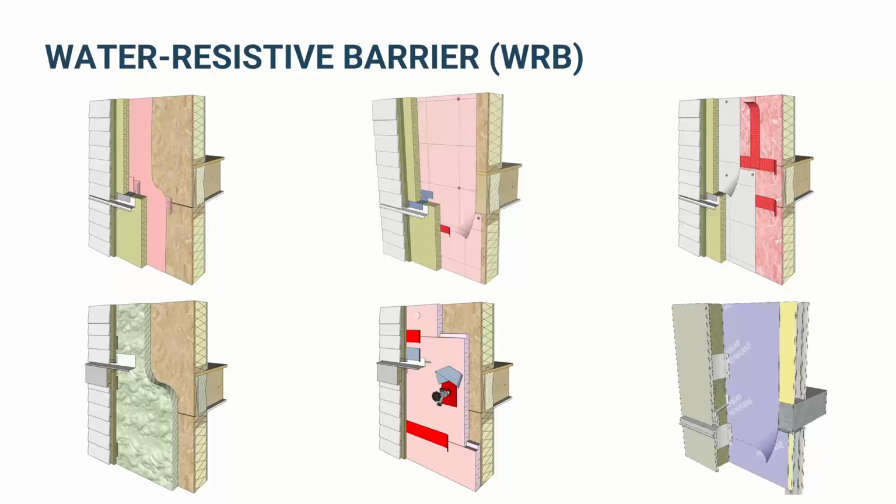So there are sheet applied, there's self-adhered versions or mechanically fastened versions. There's foam insulation, either sprayed or taped boards. There's fluid applied systems. Lots of different ways to do this. Again, this could be its own presentation, but the key here is just that they're all water resistant barriers, and a lot of them are actually also air barriers, and so they are detailed to be sealed airtight. In some cases, in some assembly configurations, they're actually also the vapor barrier. So we see that sometimes where there's all exterior insulation, and that membrane, the WRB, is really doing three different things all at once. It's the water resistant barrier, the air barrier, and the vapor barrier.